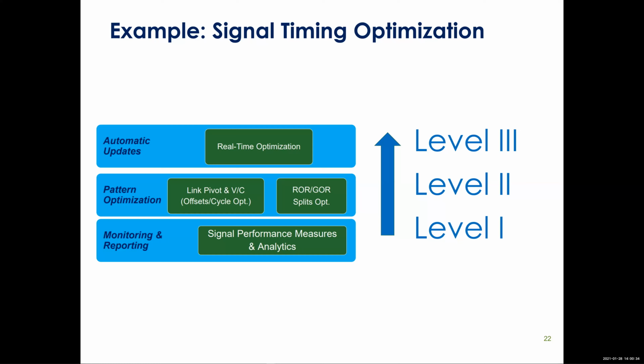Then you can download that to the intersection and watch it run for about another week. You'll run analysis on it, determine whether it did any better or worse. And if it did better, you can run another analysis, and eventually you're going to fine tune it over several weeks to a point where it's running very efficiently and not doing many updates.